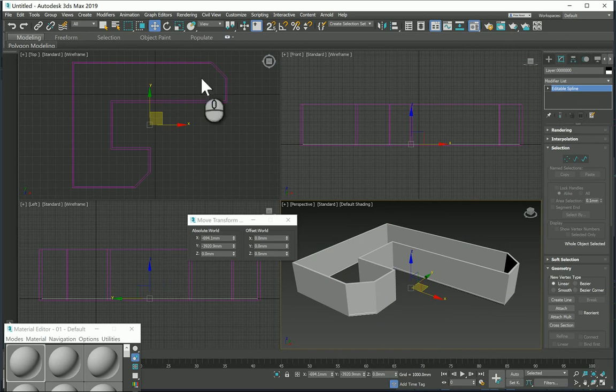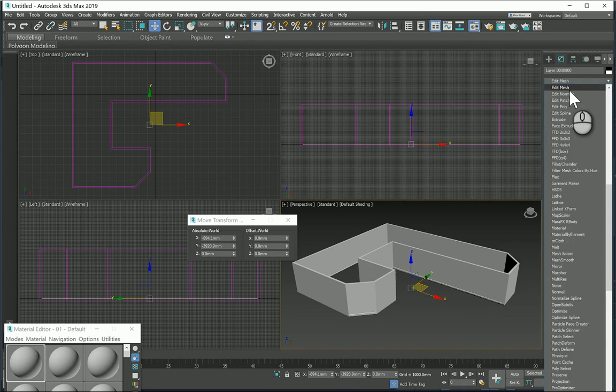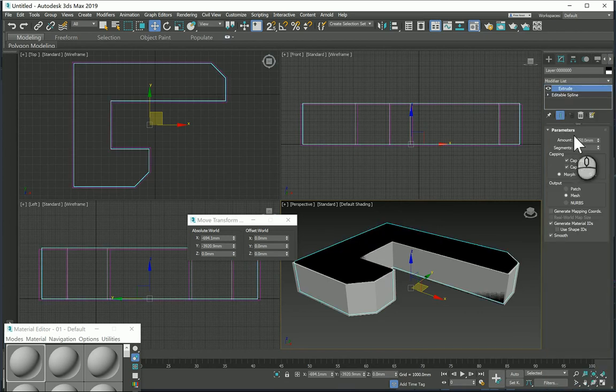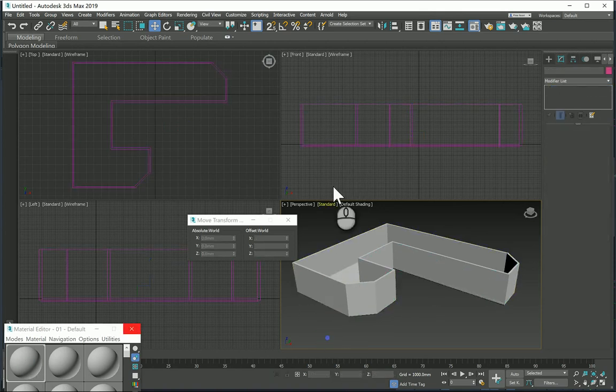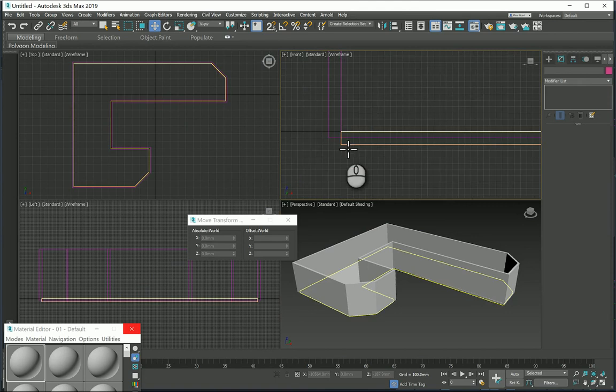Now we said level horizontal surfaces following rule number 2, which is the Z value should follow AutoCAD, so it's a happy coincidence, it is 0. Just add an extrude for it, and the extrude I will use is -200. And just gonna drop the material on it. Have a look at what you're doing in the elevation or in this side.